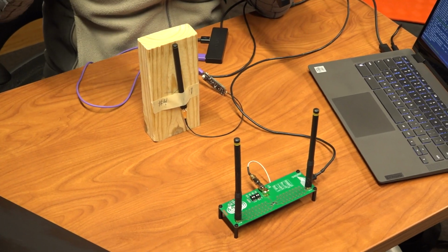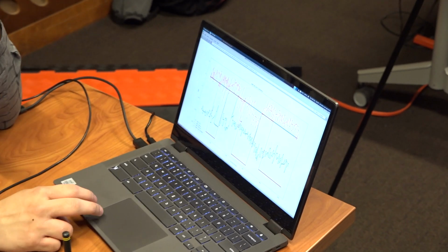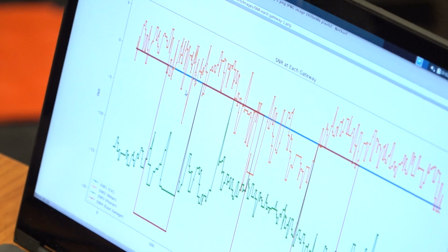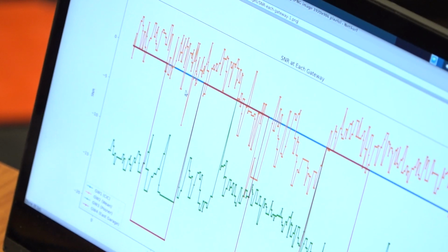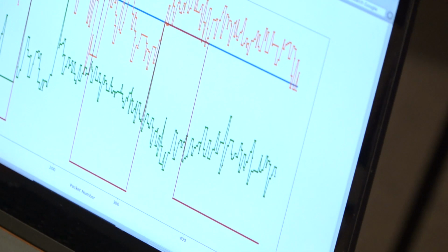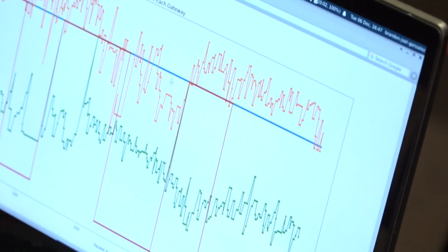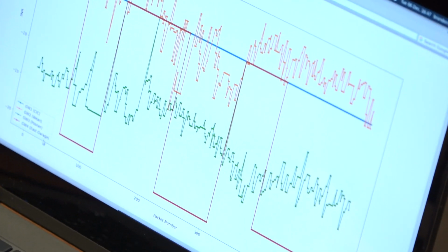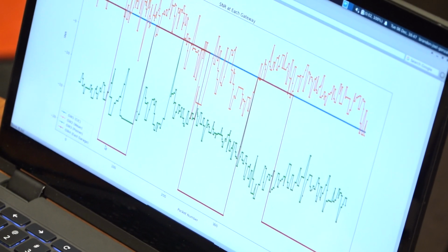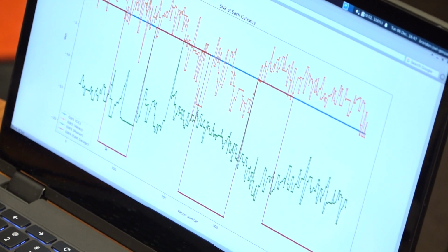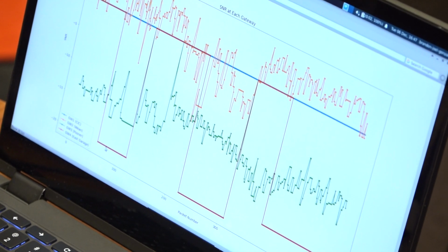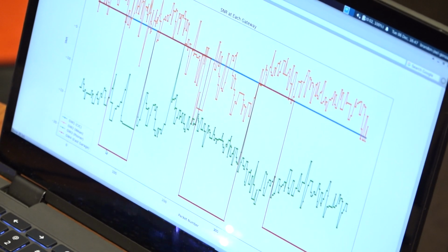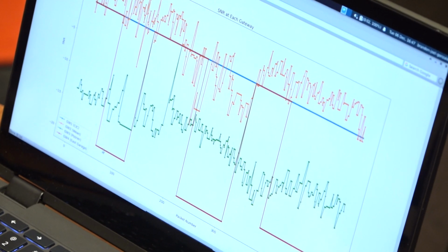We are logging the SNR values, and then we essentially plot them. Just to explain what's happening in this plot, we're plotting four lines, and they are the SNR values for the packets received at each gateway. In blue, that's at the CIC. In green, we see the gateway on Posner Hall, and then in red, we see the gateway at the East Campus Garage. As you might expect, the East Campus Garage is on the other side of campus from where we are, and there's a lot of attenuation as the signal travels through buildings. So as we expect, we're getting a pretty poor SNR.